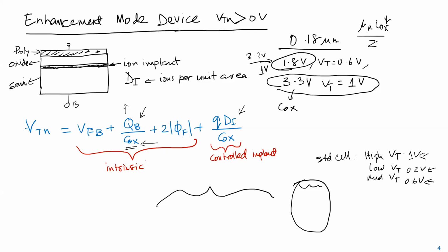Sir, one question. You are saying that COX will change. That means from a fabrication point of view, the thickness may be constant? No, no. Santanu, he's saying you actually change the TOX, and that's where you create this high voltage device, but then you lose the speed, because your COX decreases.